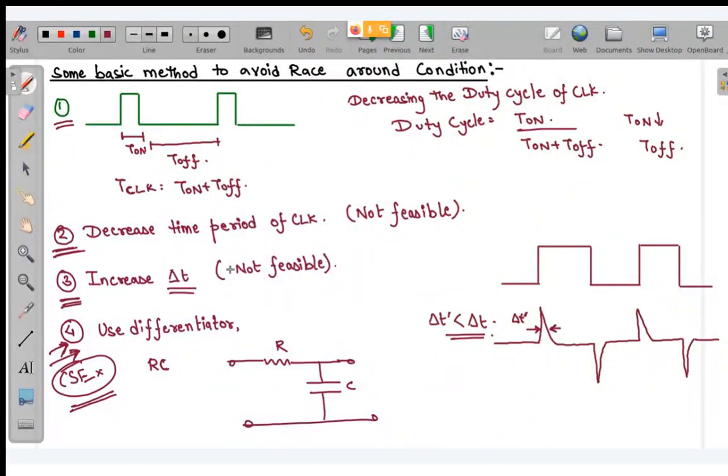In digital logic, we want all the elements to have the least amount of propagation delay, but here we are actually increasing it. And if you are from an electrical background, R and C, resistor and capacitor, are very bulky components, and digital circuits are very compact. So we are not going to use this.